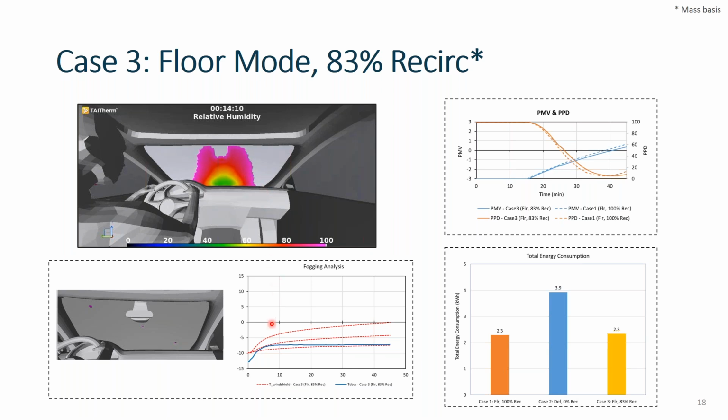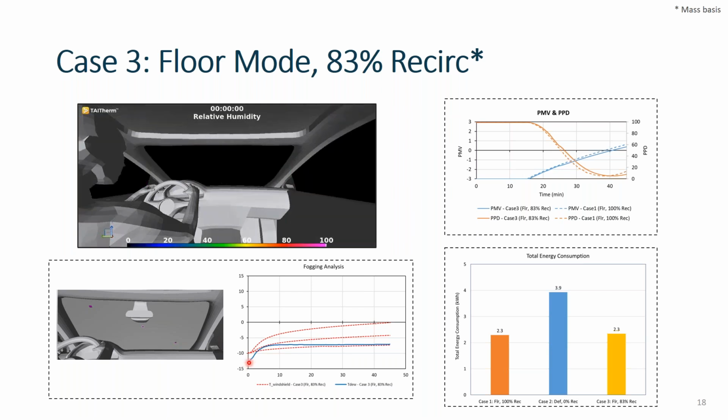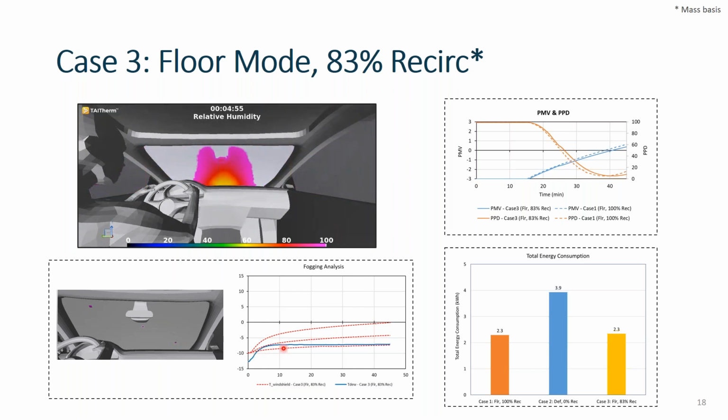So what we can do is look at this in a different way. I've plotted below here the dew point temperature in blue. Again, this is basically just the moisture content. Initially our moisture content is quite low and our occupant is entering the vehicle, so he's adding some moisture, and then we achieve some steady state value as it blends with our fresh air intake. In red, I'm plotting the surface temperatures of our interior windshield, so these 3 surface thermocouples over time.